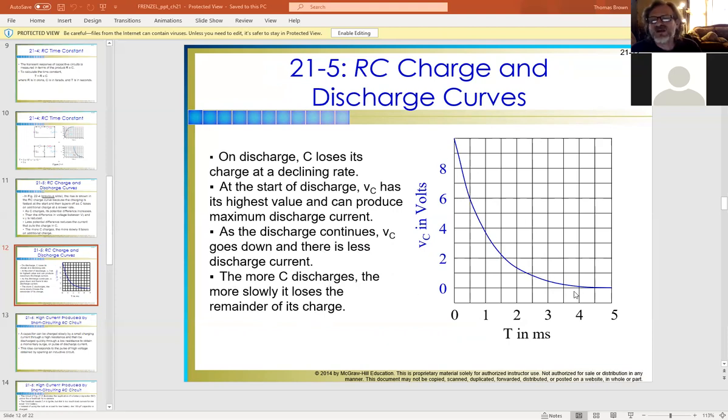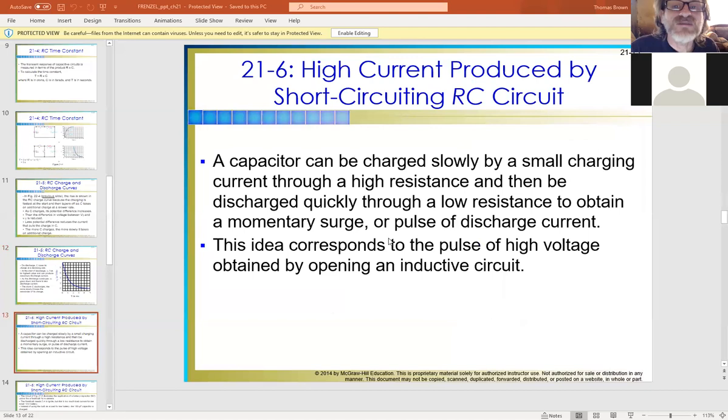And that's what he is showing us, because basically this is how long it takes for that thing to fall from like 10 volts to 0 volts: 5 milliseconds overall. But we can see, each time as we go further out, it goes a little slower. In fact, look at that. To go from a little over 0 down to actual 0 takes it a full millisecond. And the capacitor hasn't changed. It's still the same component it was, but it's just part of the effect of these things.